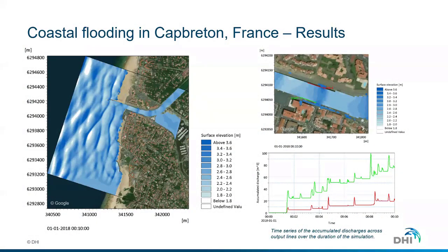is overtopping happening parallel to vertical walls. So that is something that the overtopping manual EurOtop actually can't really consider. That is something that we are able to resolve using this MIKE 21 Wave FM module. So we can see up to our right that there's a wave that is propagating along the channel, and we see that it overtops parallel to the side that it is propagating through. So that is a case where the overtopping manual can't really help or doesn't have guidelines for.